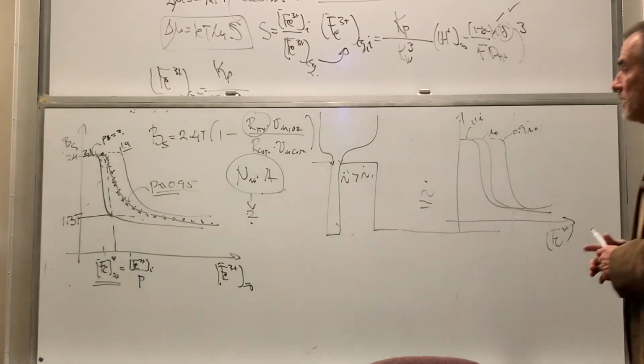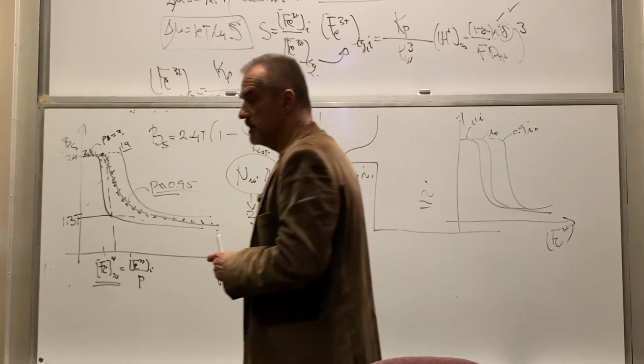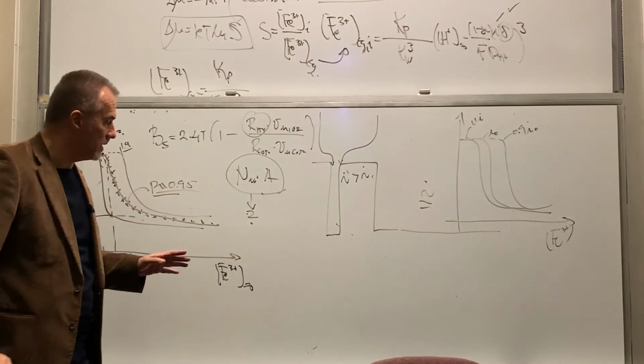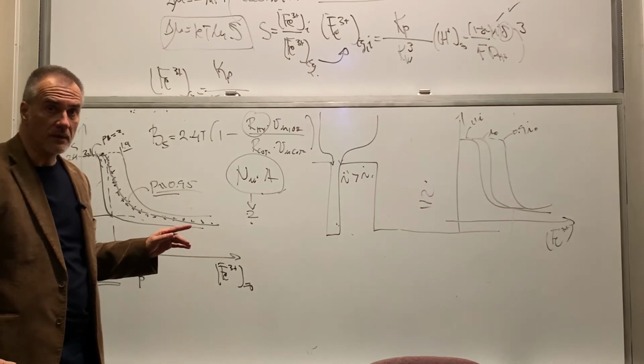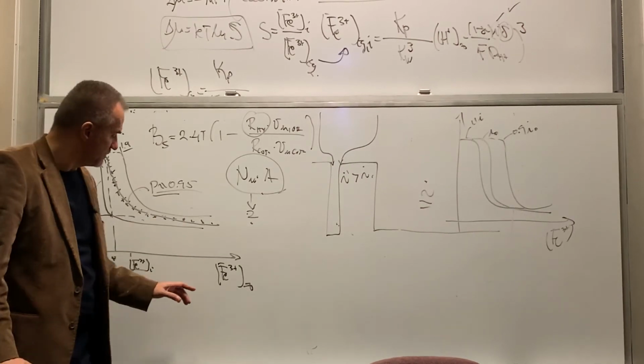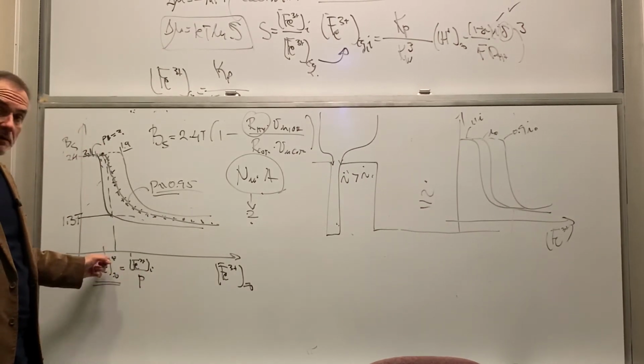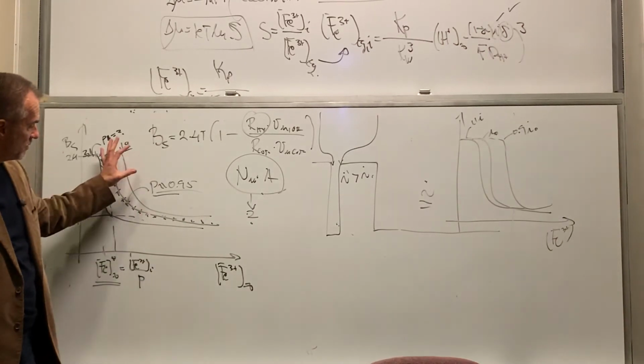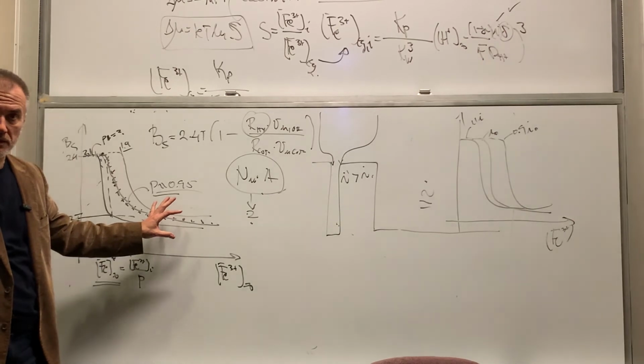So when you do electrodeposition of magnetic alloys, this process is with you, and you have to be aware how you design your process in terms of having iron 3 plus in the solution under control. Because if you're above, your magnetic moment will be less.